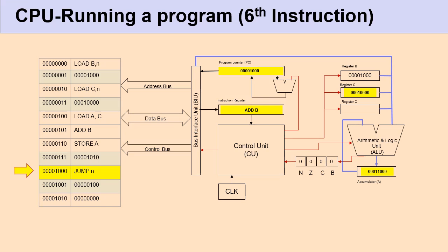So in this case, if you look at the program, you will see that that address is 0100. If you look at the program listing, that's one of the instructions that we have executed earlier. So it jumps to somewhere in the middle of the program, and the instruction at that particular address is the add instruction. So again, after executing this jump instruction, the CPU will jump to the add instruction and start executing from that point onwards. In that loop, it will again come to the jump instruction and again jump back to the add instruction. So in fact, this program is running in an infinite loop, adding register B to register A and storing that result in the specified location. If you look at the program carefully, you will understand that.